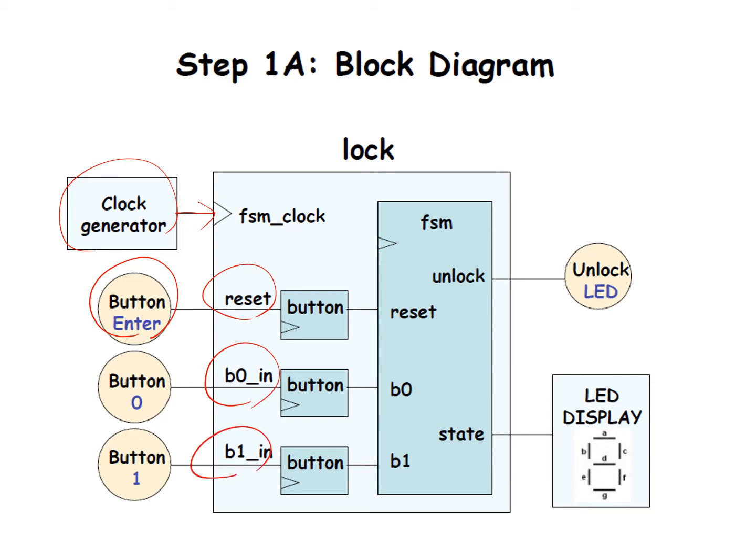As we know, these button signals are asynchronous inputs, so we put in a synchronization block. Here we use a single synchronization flip-flop.